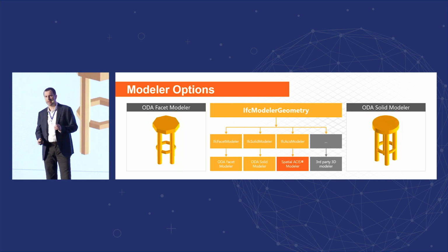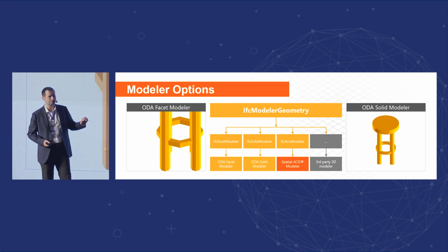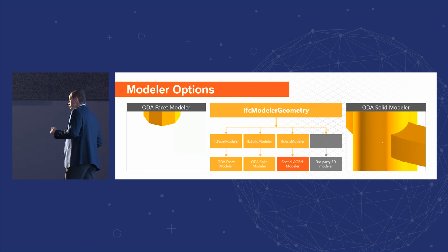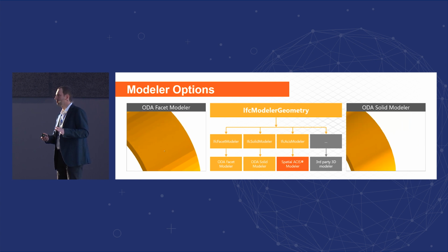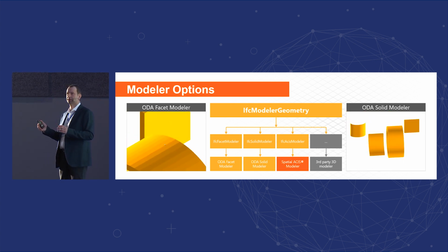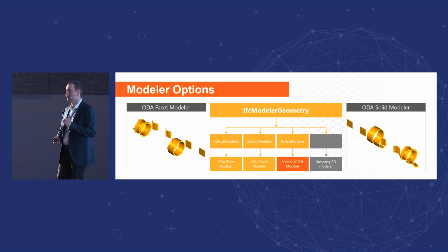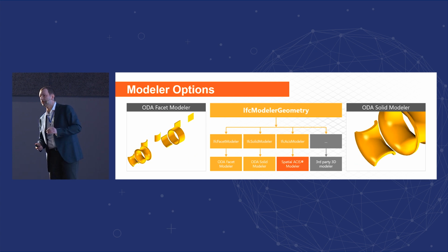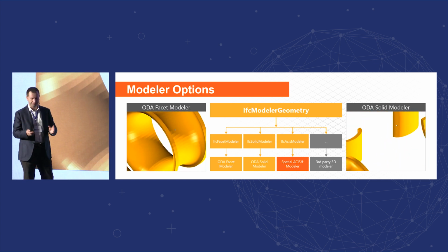Another difference, and I think a significant difference from other IFC toolkits in the market, is that usually if someone implements an IFC toolkit, and for geometric entities supports conversion of implicit geometry to explicit, they use one chosen modeler, a B-Rep modeler or a Facet modeler, and overall you are stuck with one type of geometry.